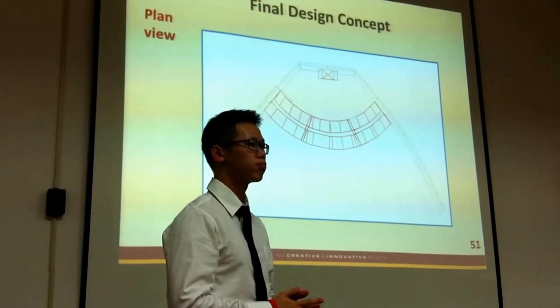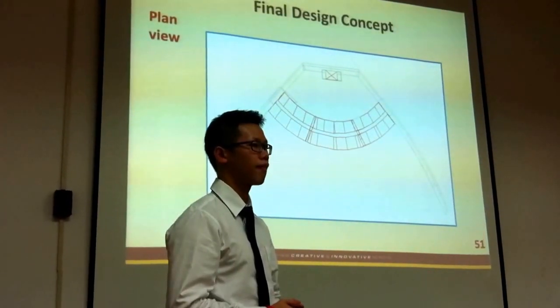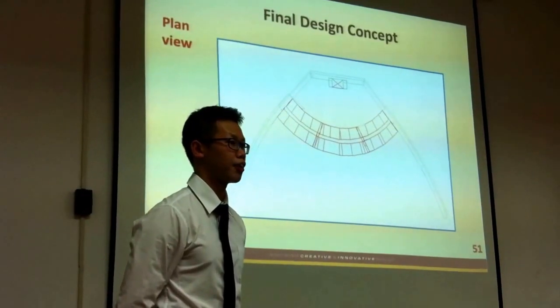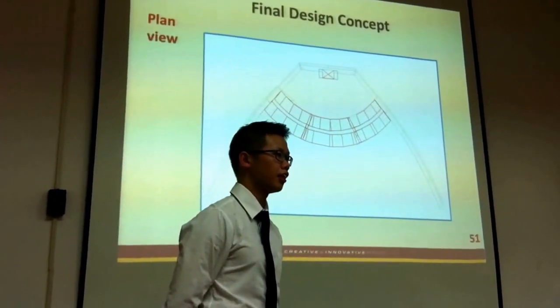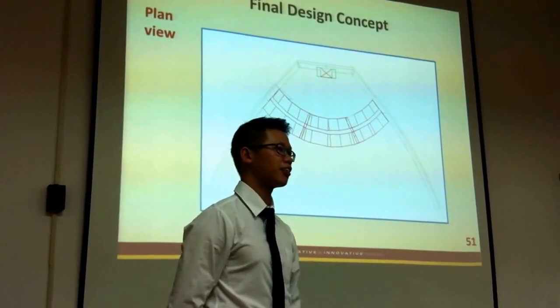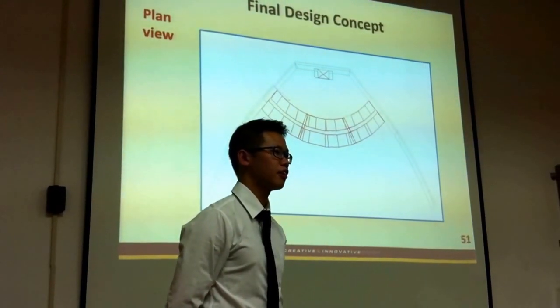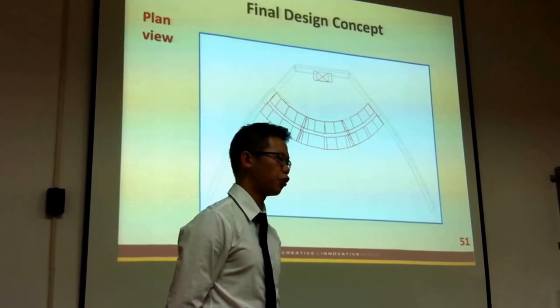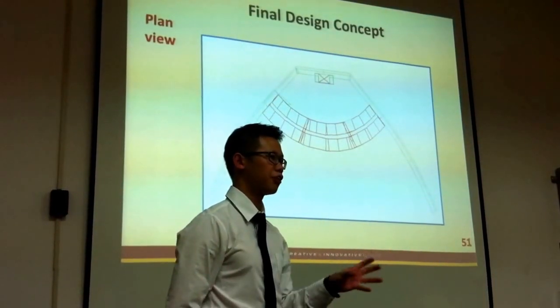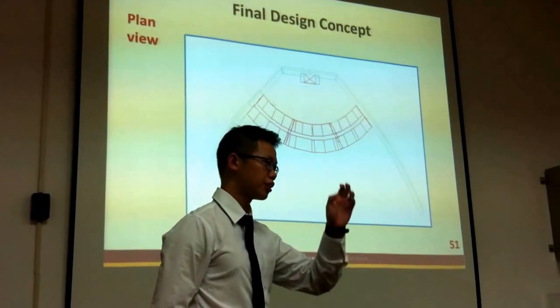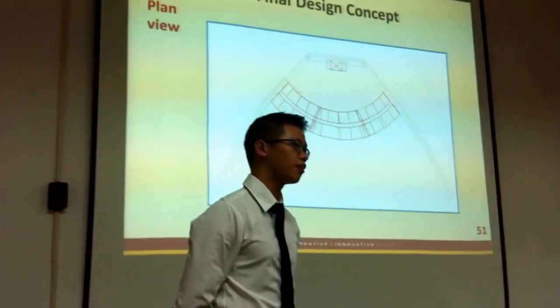When the ramp angle is 30 degrees, the overtopping rate is 3.67. The rate, volume, flow rate. Volume. Yes. Okay. So when it is 40 degrees, it's going to be more, isn't it? Yeah. For the lower one, because the 40 degrees one yields higher overtopping rate for the lower reservoir. 30 degrees yields higher overtopping rate for the upper one.